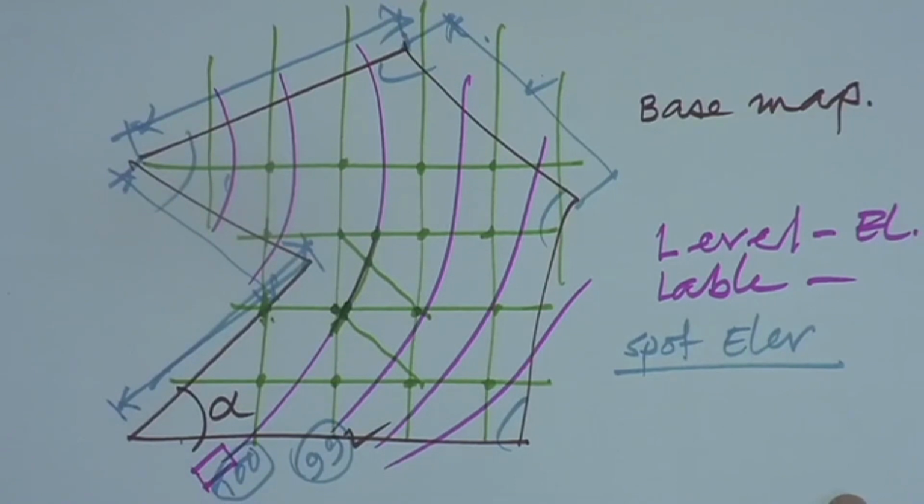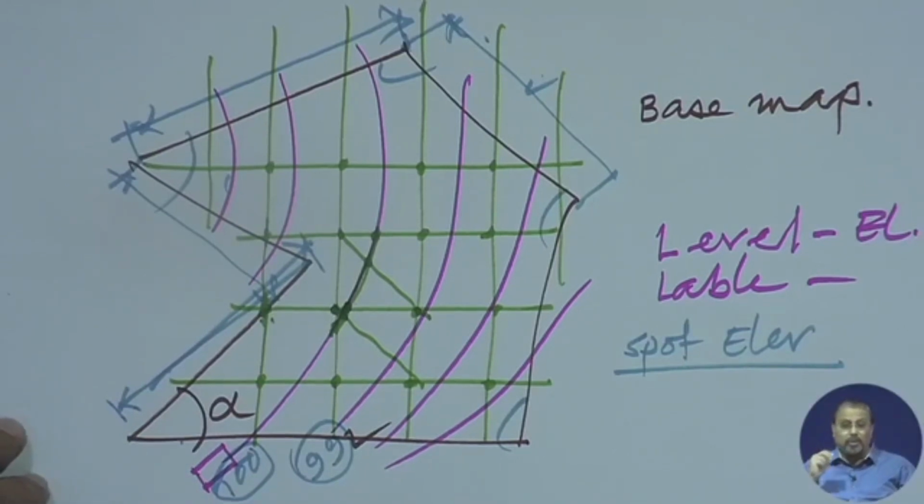You can only do it when you have gone to the site, felt it, you have seen it, you have a photo documentation, and at the site itself you have a feeling, visually interpreting and perceiving, and then through comprehension and intellection, you can say, if this site is so flat, I need not take intermediate levels. So my distance between one particular spot elevation point and the next elevation point may be quite far away, because in between if I do take any other points, it will make marginal difference in the elevations.